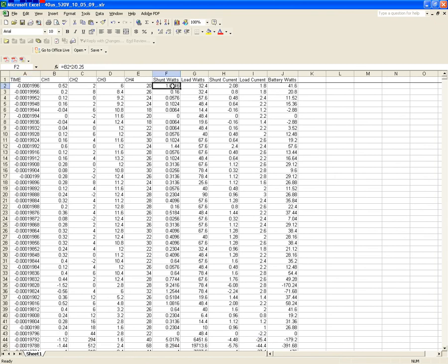For the calculations, we have the shunt watts, column B squared over the resistance, which we know is a 3% 0.25 ohm resistor. So this is our power, standard equation, E squared over R. What is column B? Column B is our shunt. That's channel 1, put right on the source. The other side of the shunt is at the B minus, so this represents the voltage drop across that resistor, which gives us the current that's flowing into the battery on the negative terminal.